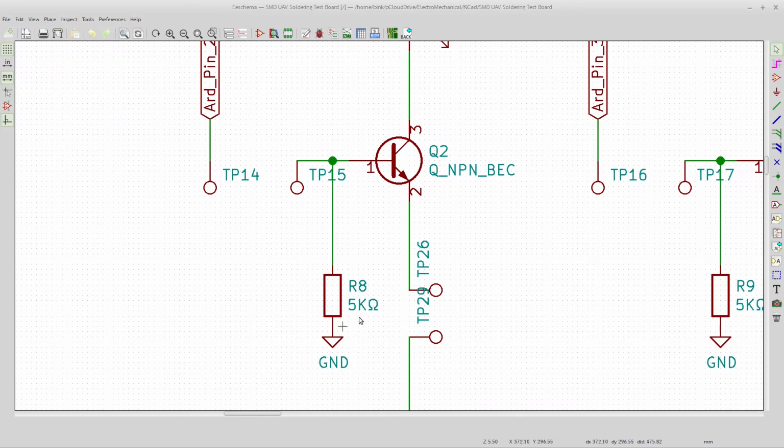Now, if we keep increasing the restriction, pretty soon you're going to end up with a situation where it's almost like not even having this, where you can end up with a bit of built up energy right here that holds this switch on, and very slowly the energy trickles to ground through the resistor. So that's going to make, let's say it's a light, that's going to make your light stay on a little bit longer and then slowly fade out, possibly something like that.